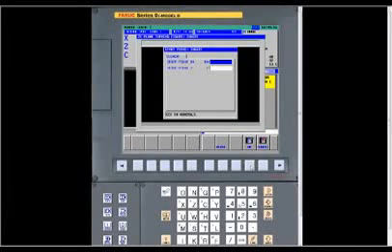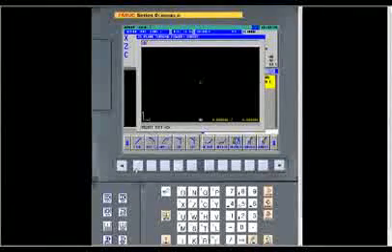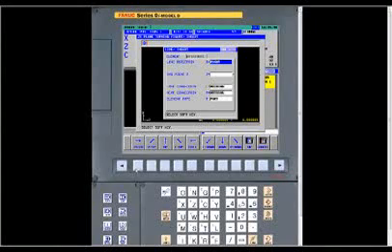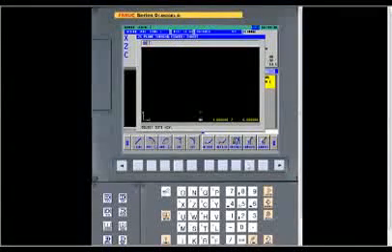So again, now we have to go describe our profile. Now this time, we go in, we're going to start at 0 again, and 0 and Z, and say OK. And then we'll do a line, and our diameter going up is 1 inch. We don't have to put anything on the next 3 just like before.